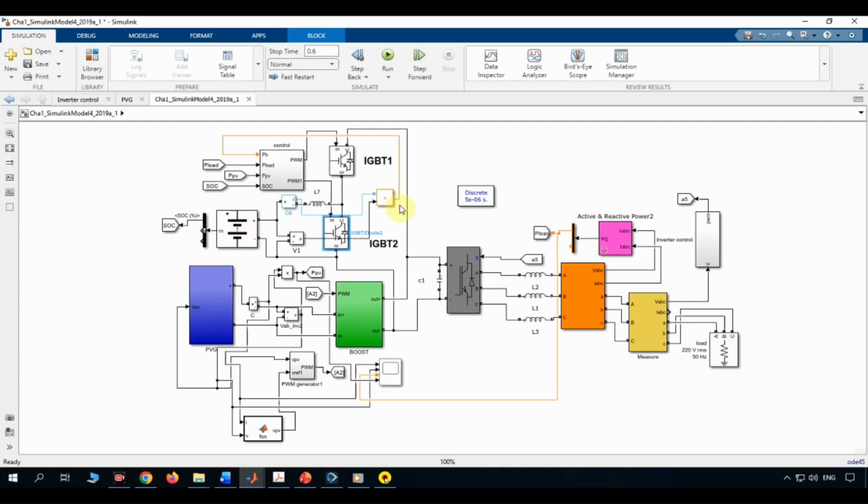Finally, all of that combined DC power, from the panels and the battery together, reaches the inverter. This is the stage that converts direct current into the three-phase alternating current that an actual grid or AC load needs. A voltage control loop inside the inverter keeps that output locked to the correct amplitude and frequency, and a final measurement block continuously reports back the real and reactive power being delivered. That's the full journey: sunlight in, usable AC power out, and every single stage in that chain is its own small engineering problem, solved with real equations and real control theory.